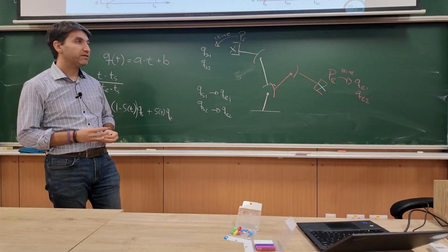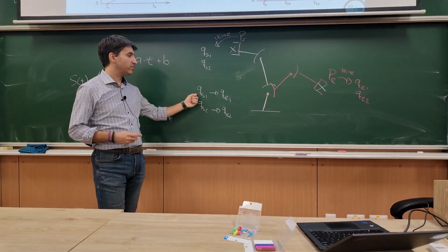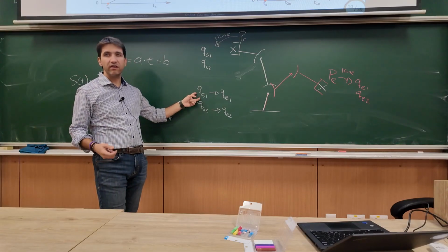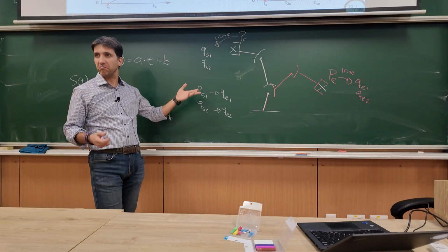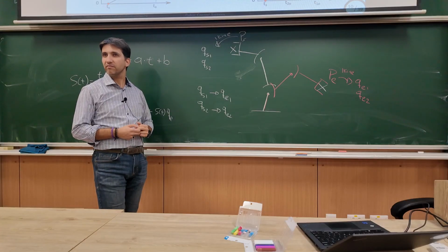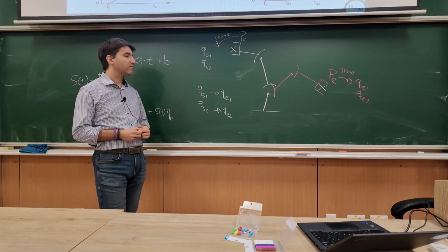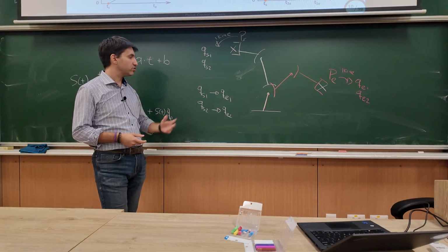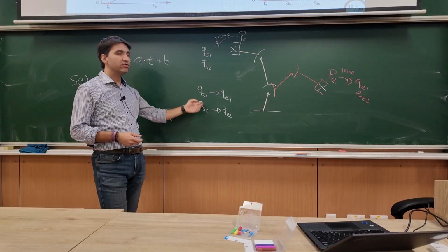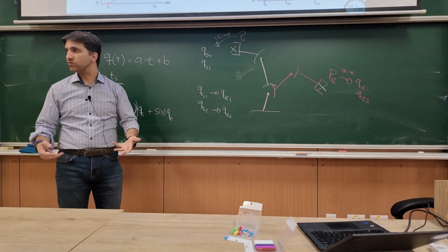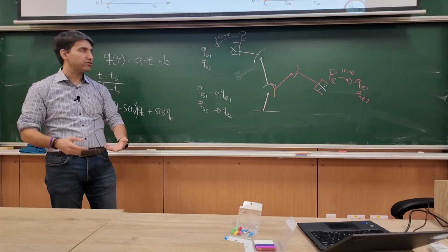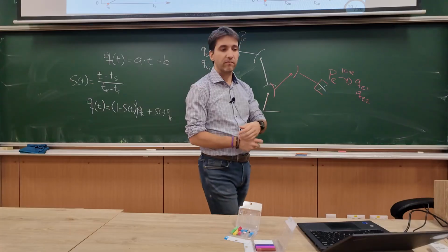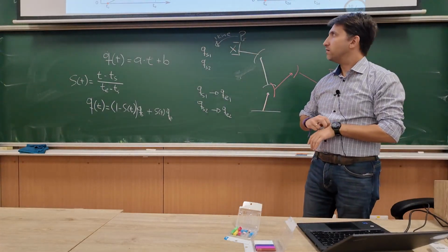Do you remember the forward kinematics? This basically is the relationship of Q to the end effector position and orientation, right? Is it a linear relationship or non-linear or what? It is non-linear because it depends mostly on sine and cosine. Right, exactly. So the position, you remember the angles were always inside cosines or sines, right? So it's a non-linear relationship. So if these move linearly, the end effector will not necessarily move on a line. Will for sure not move on a line, right?